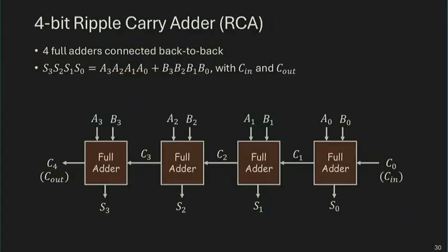Now, I'm just representing that 1-bit full adder as this block symbol with 3 inputs. You have 2 from your input data, and one of them is a carry in from the previous bit, and then it produces a sum and carry. There's an arrow representing the direction of data flow. Each full adder sends the carry out to the carry in of the next full adder, and that forms a carry chain. This carry chain allows us to connect multiple bits together to create a wider adder.